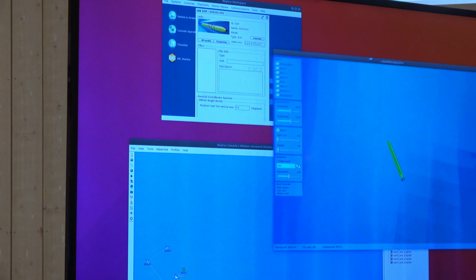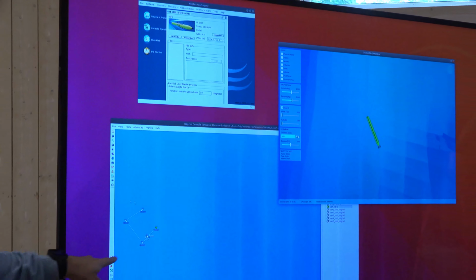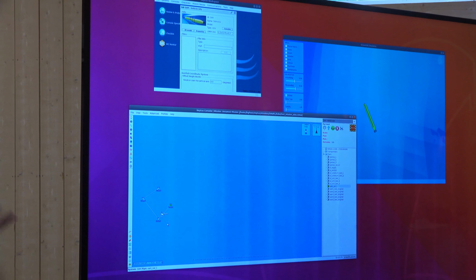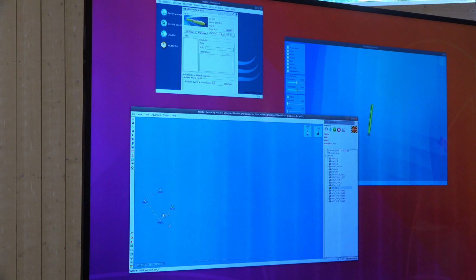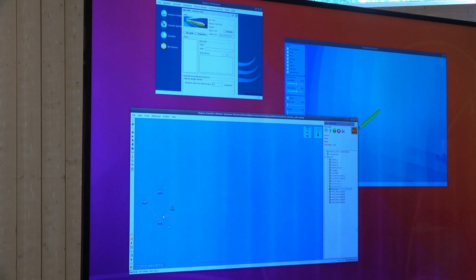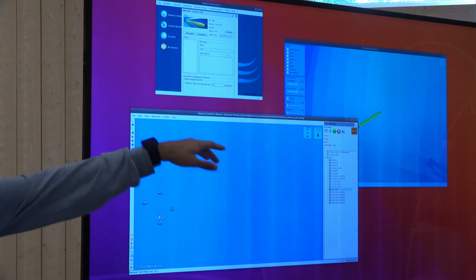And so that you can see what the robot is doing, and on the other side you can see the mission. So if you see here, now you can see that it displays it up and down. So we have a behavior tree that refines the waypoints, but we also have a path planner which doesn't work so well right now, which creates a spline between the different waypoints, but that's part of work in progress.